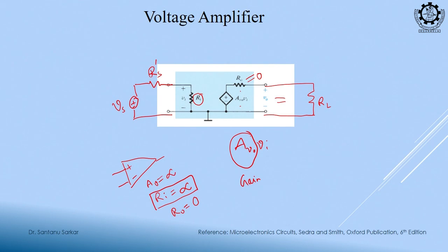So in op amp you have studied that voltage gain is infinite. So that is my AV0, we want it as high as possible. Okay. Input impedance should be infinite. Now, what is the meaning of infinite? It should be much larger, this Ri should be much larger than Rs, clear.